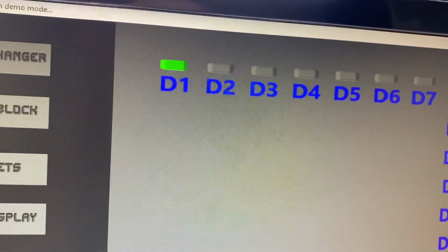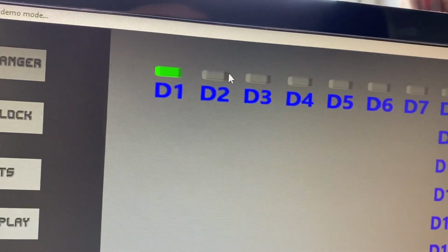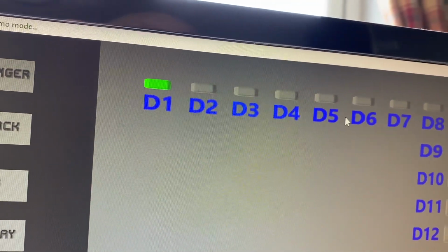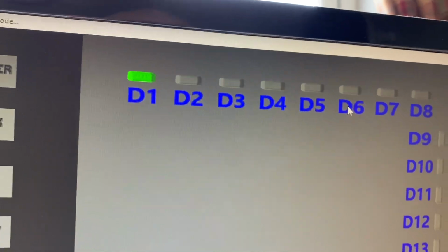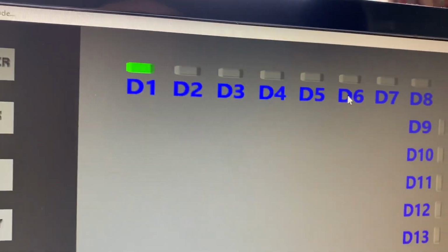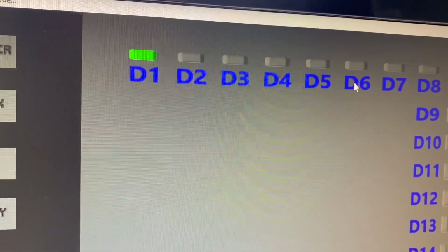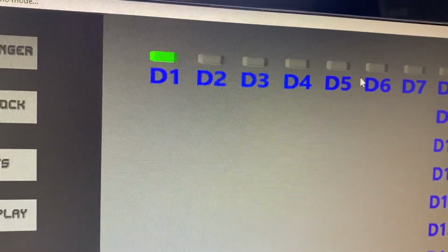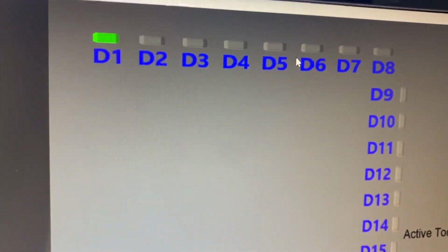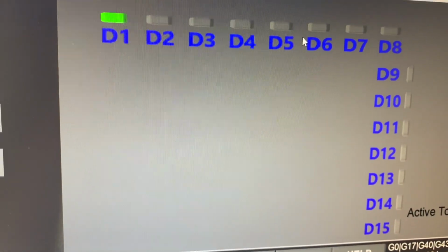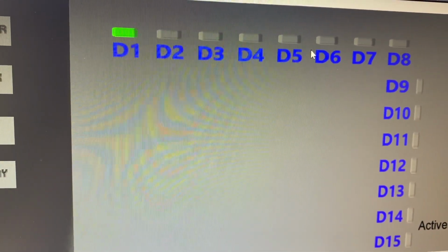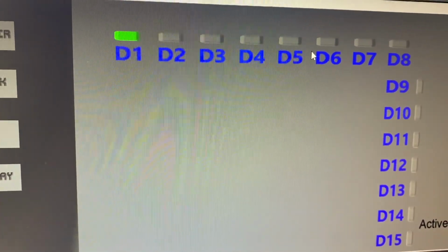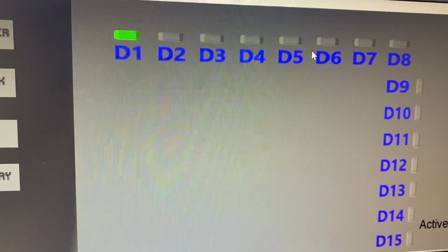All right, so if we had the 5 on, we would drop drill 1, 2, 3, 4, 5, and 6 would all drop down together. If we had it selected in the code as 571, it should be drill 1 plus these positions. Now obviously in a drill block, you have to set all of the tools the same length. So if it's a 5mm tool going in there for, say, shelf pins, all the tools get set to the same height.